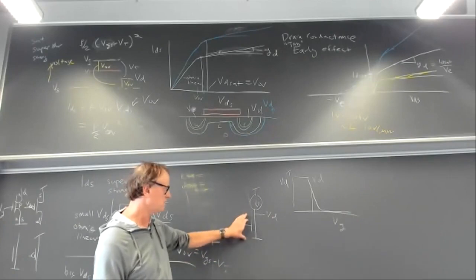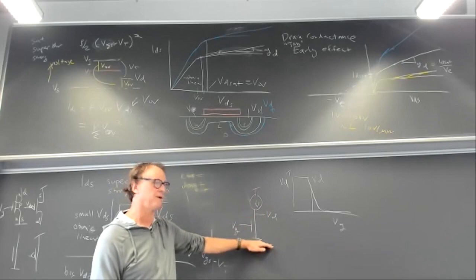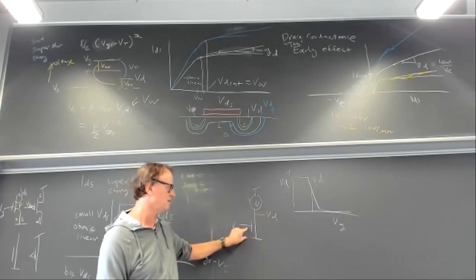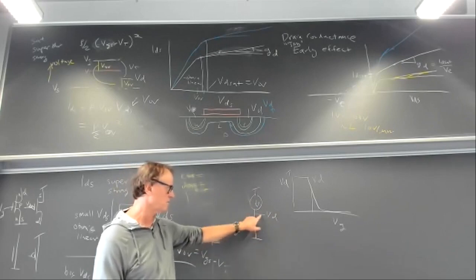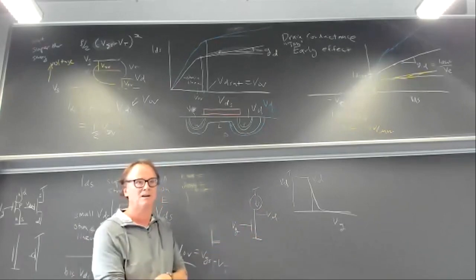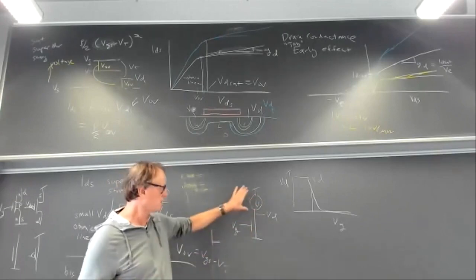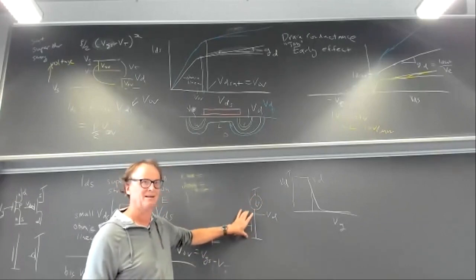On the other hand, if this current is bigger than this current source, then charge is getting pulled out, and it must go down until this transistor turns off. Eventually, this transistor will turn off, right? When the VDS gets small enough, it won't conduct any more current. So you'll have two kinds of current sources, a current source fighting with a current sink.